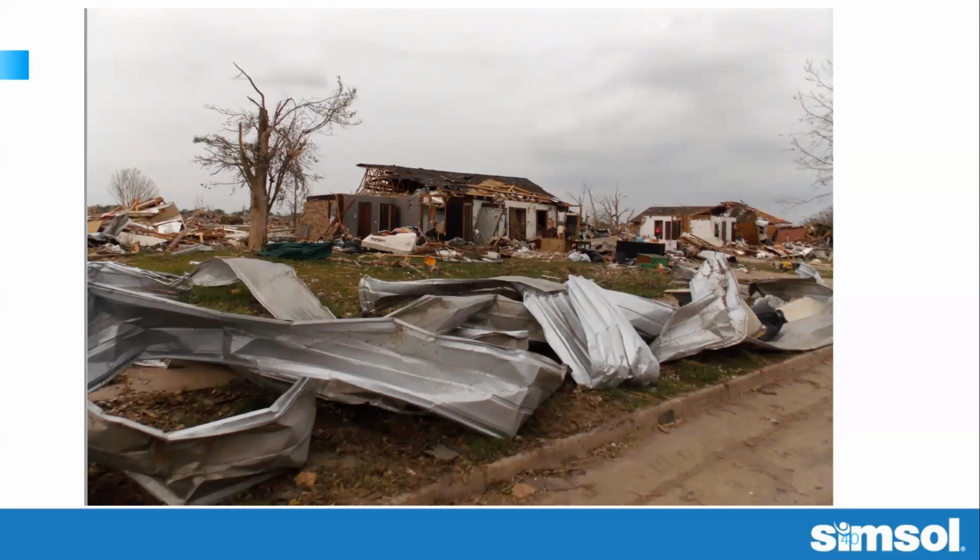But this photo is a good indication of what we were talking about earlier about how the structure comes apart. You can see here, the garage appears to be on the left side of that house in the center of the photograph. The garage door is gone. The roof over the garage is gone. And that's a lot of what we were seeing, particularly in Hurricane Michael, a lot of the same damage. The garage door either was pulled off or pushed in, which allowed wind access to the building, and then it took off the garage wall. It got into the attic space above the garage, took the roof decking off, and then once it was into the attic of the house, the ceiling finishes are the next weakest link to go. And once it's into the house, windows, doors, all kinds of things start happening and breaking.